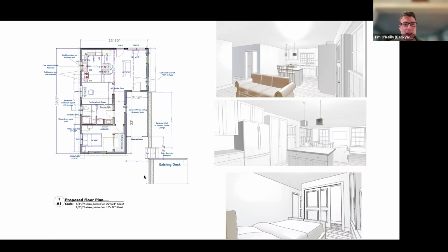Typically that needs to be at least 3 feet wide, if not 3.5 feet, thinking about a railing. And depending on how deep that basement is, if we're doing a straight staircase, it's normally about 13.5 feet. We can also look at doing an L staircase or a U-shaped staircase. So that's my long ranting answer, but it's going to take somewhere between 100 and 200 square feet, depending on where we're at, to get in there. Or that's too much. 75 square feet is a pretty good one.